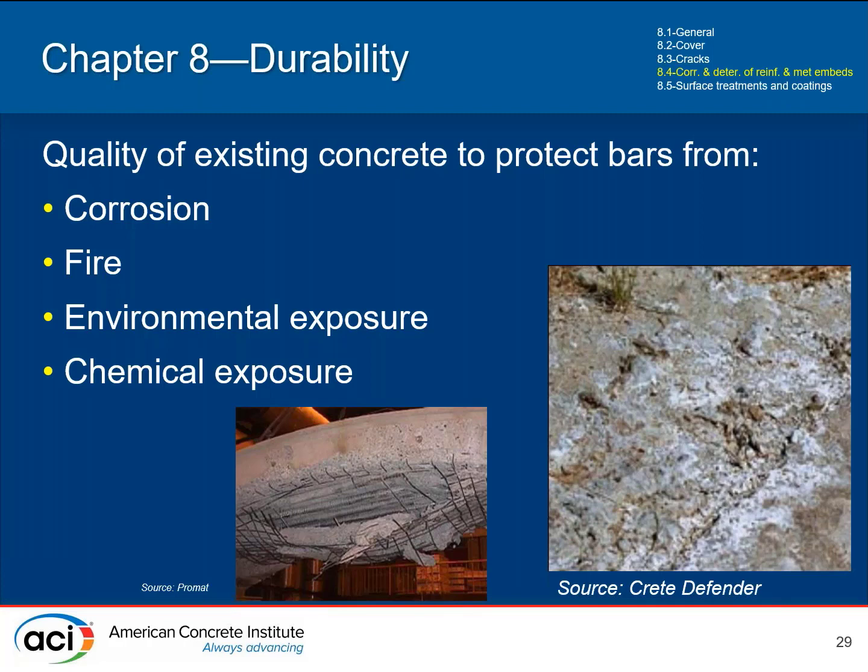fundamentally, concrete is super important. I'm not dismissing the value of concrete. This is the American Concrete Institute, but the reinforcement is often the more critical item in the structural performance. So save the reinforcement is really the objective here. If you lose some concrete from scaling or freeze thaw damage, there's a lot of other concrete there, to a great extent, not always, and take everything I'm saying with a grain of salt.